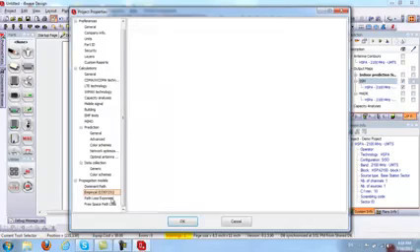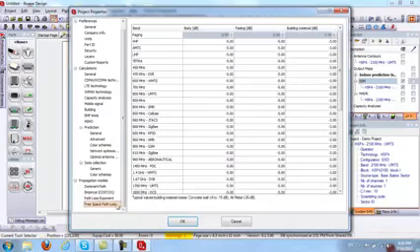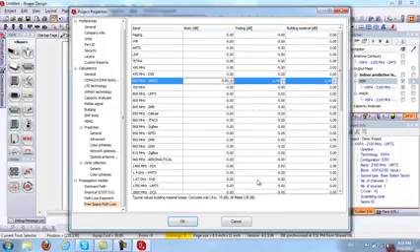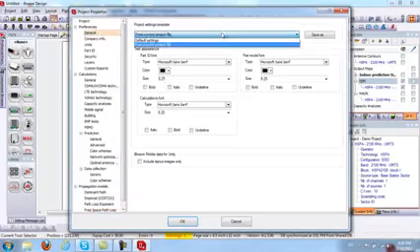And then you have your path loss exponent and your free path loss. For example, under the free path loss, here you have your body, fade-in, and built-in materials. You can take that into consideration when running your prediction maps. You can change these values should you want to. So again, once you have finished setting all your project parameters, you can go to general and you can save them as a template.